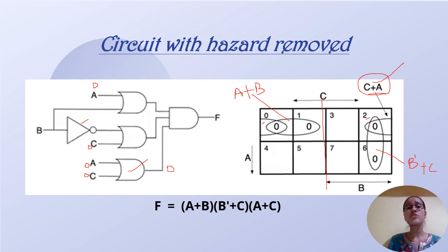And if any one of the inputs to the AND gate is 0, then the final output will always be 0. So our expectation is satisfied that there is no static zero hazard appearing, because we won't get 1 at the output. We always get 0.